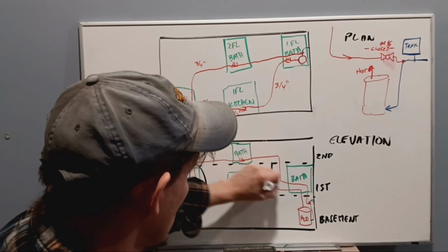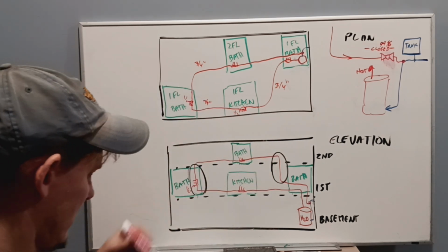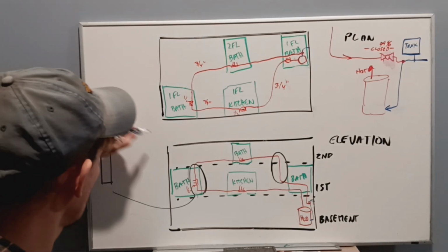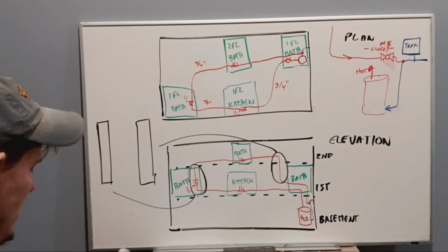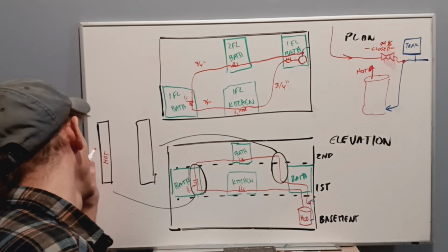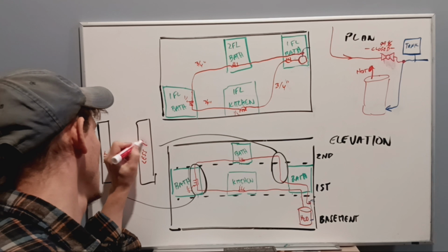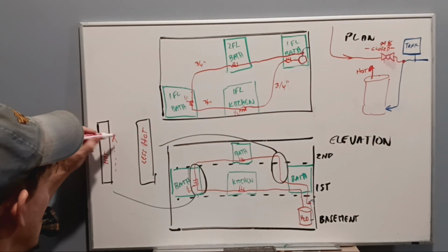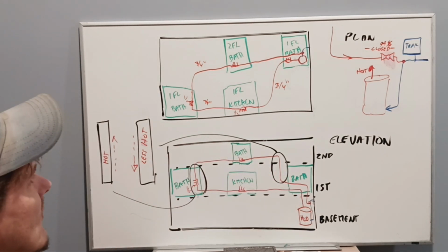Interesting, but how does it work? Let's look at these 2 sections of PEX, the portion where the PEX goes from the first floor to the second floor and then back to the first. Inside these tubes is a volume of water. Further from the hot water supply, the water will be naturally cooler as it loses heat to its surroundings. So, that section of pipe has cooler water, which is more dense, and therefore very slightly heavier than the comparable water in the pipe going to the second floor.